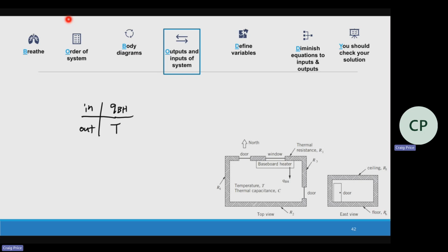We are modeling the heat loss for the doors and windows. Those are all lumped together into each wall's resistance. So R1 is going to be less than R2 because it has way more ways for that air to leak out. Now, one thing we didn't mention was under the doors, typically there's a little crack, and that means that air can pass in and out.